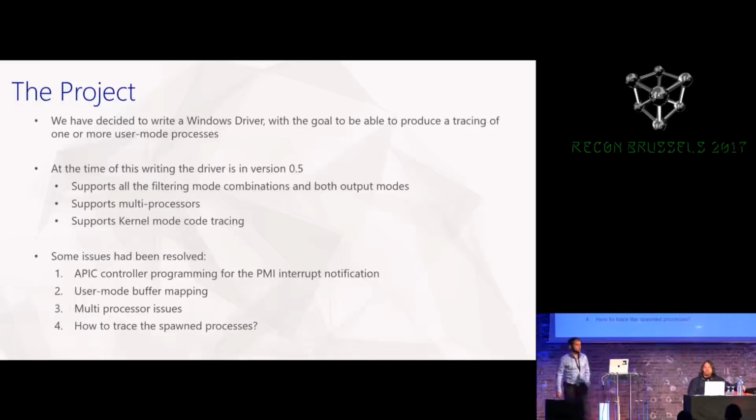In developing this driver, we had to overcome a lot of problems. One of the biggest problems was the mapping of the PMI interrupt, because there was no documentation at all for how to do that. And even the multiprocessor support, because you have to manage and you have to enable the processor trace once in each processor.